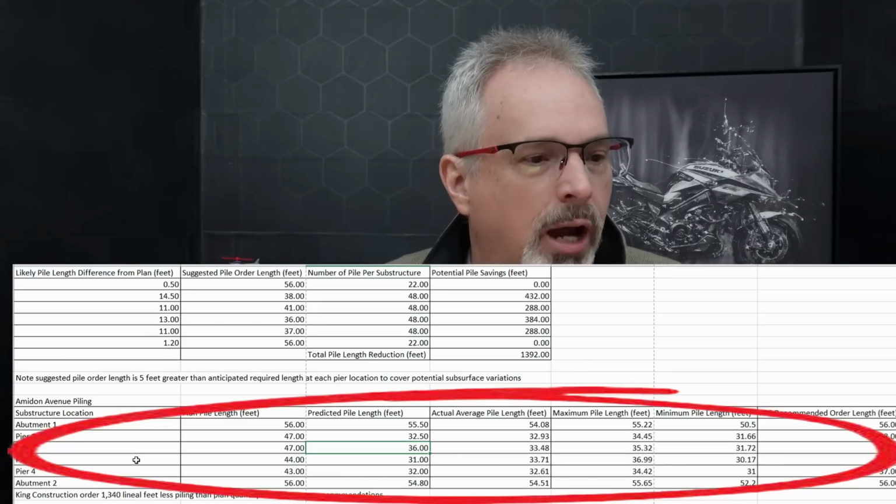And so sometimes contractors aren't sure what kind of hammer they need to drive a pile to a certain capacity. When you select a hammer, you don't want to have too many blows because it's very time consuming to install the pile if you have to have too many blows per given amount of penetration. And you don't want to have too big a hammer because then it's just too much energy, you risk damaging the pile. So let's go back and look how this job actually turned out.